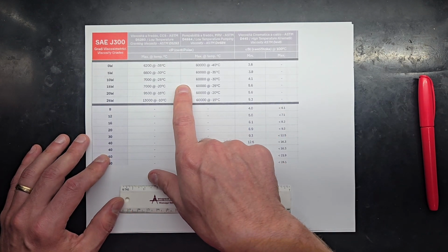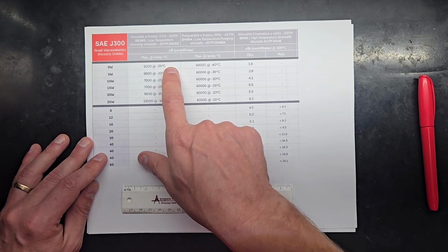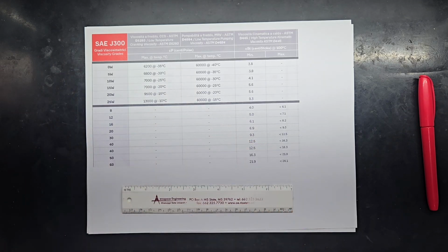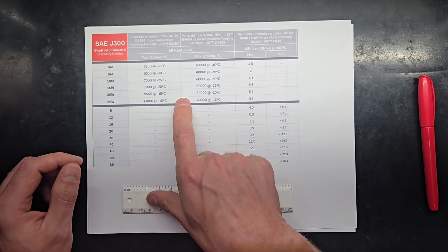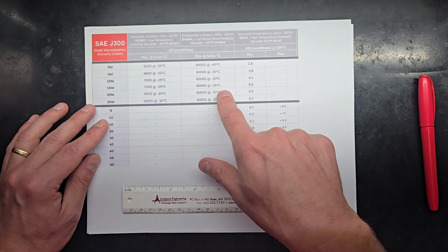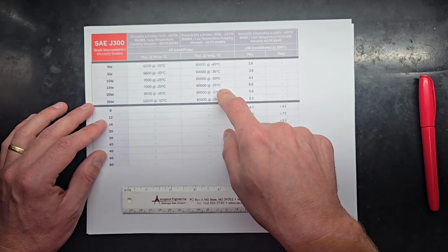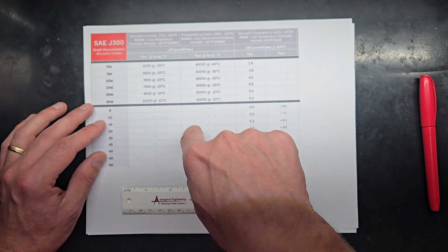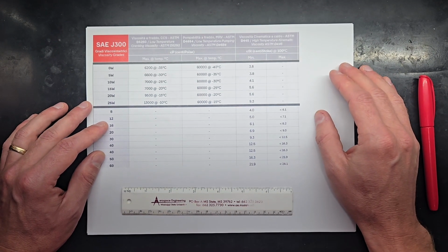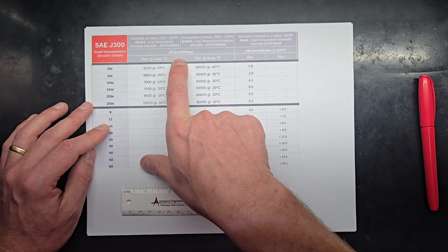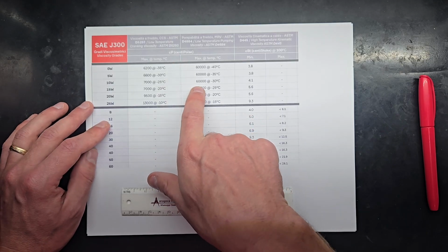For absolute viscosity, flowing any of these at these very, very low temperatures, it's going to have a fairly high time domain. So the way the absolute viscosity is measured is you have, again, a volume, you cool it to the temperature, and then you place a disc or a rod into that, and the disc or rod is rotated. And the torque or power that it takes to rotate the disc or rod is how we establish its absolute viscosity.